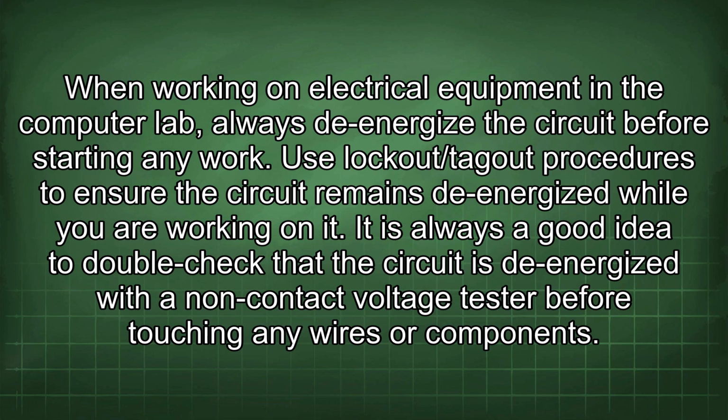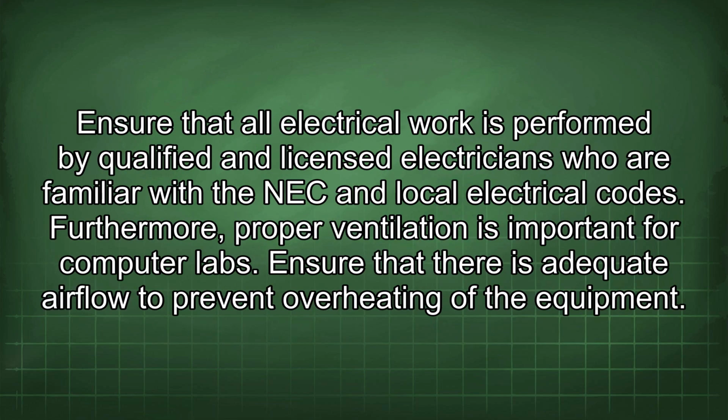When working on electrical equipment in the computer lab, always de-energize the circuit before starting any work. Use lockout/tagout procedures to ensure the circuit remains de-energized while you are working on it. It is always a good idea to double-check that the circuit is de-energized with a non-contact voltage tester before touching any wires or components. Ensure that all electrical work is performed by qualified and licensed electricians who are familiar with the NEC and local electrical codes.